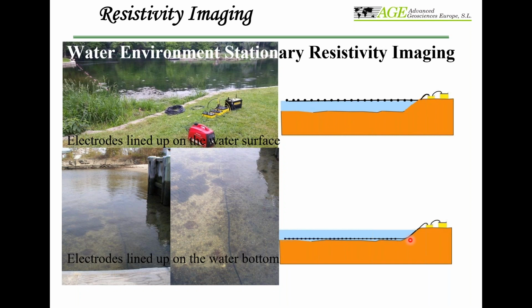So whatever it is, maybe like 1,000-meter water depth, then we can put a 1,000-meter lead-in, and then you can have here, say, 56 electrodes with whatever electrode spacing you want. Our cable can be dropped down almost 2,000 meters under the water, so the pressure and the temperature can be handled at those intervals.